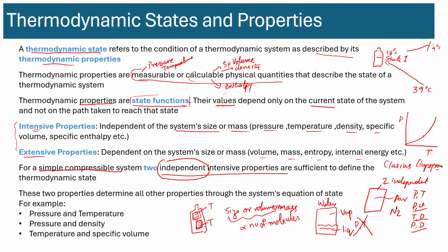Essentially, you could say pressure is somewhat of an exponential function of temperature, based on the Clapeyron equation. So pressure is not independent of temperature for two-phase regions or two-phase mixtures in equilibrium. For single-phase gases, you can vary pressure and temperature independently.